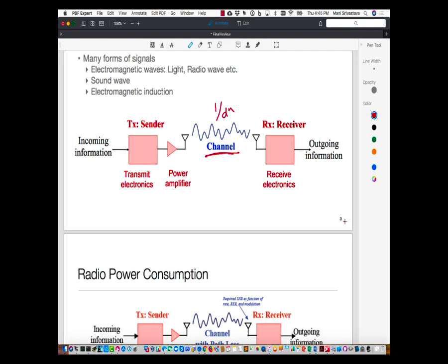If on the other hand, I'm running a temperature sensor which is sending out a few bytes every few seconds, a Wi-Fi radio would be just an awful choice. So one has to match these things. And unfortunately, architecture methods, which in this case would mean your radio architecture, buy you sophisticated architecture that leads to better efficiency, but only at higher rates, so to say.